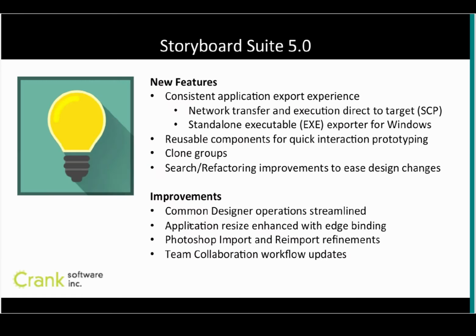So part of what you're going to see here is that we've really expedited the export experience. We've consolidated what was a growing list of export options, and we've added to that with this release. We are improving the ability to take your simulated application and drive it out to a target. If you've got a network-connected target, you're going to be able to take it from within the Storyboard design environment, export it, push it over an SCP connection over the network, and run and execute it. And that's what we're going to be doing today.